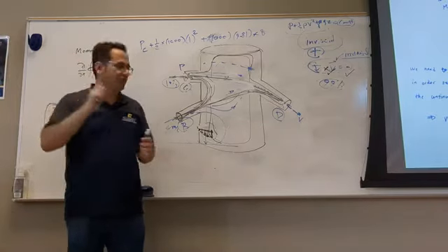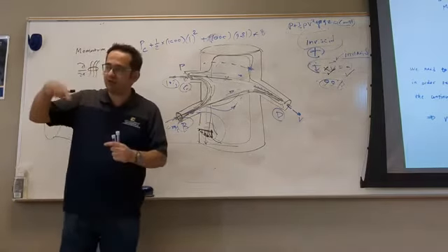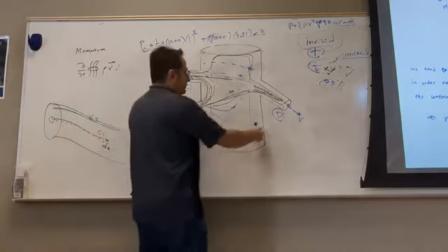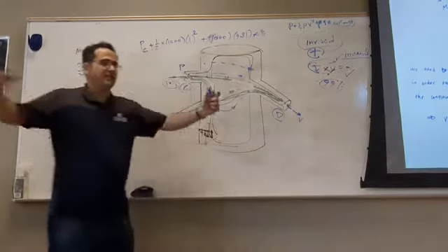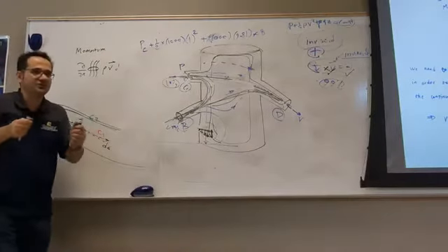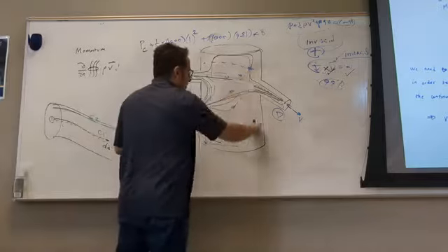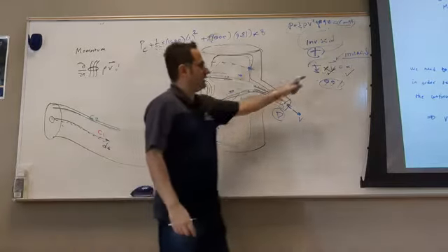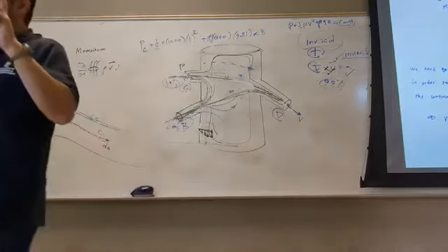But look, the boundary layer, the region where you have viscosity and rotation, is so small that you can consider pretty much the same geometry, but remove the skin. The skin of the viscosity, where you have rotation and everything. Just skin it. Then you have the same object, but totally irrotational. Then in that case, you can write the Bernoulli equation between any points without getting inconsistency.